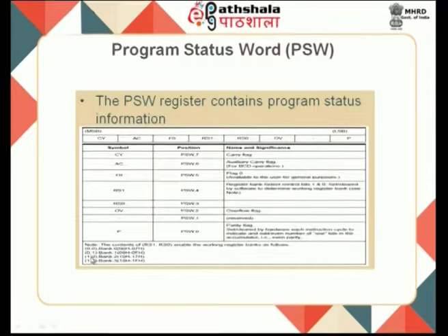What are all the addresses through which we will be using that particular register will be decided by RS0 and RS1. This is a combination, so I can make 2 bits, 00 to 11. Rather, you can look over here: 00 will be bank 0, where the address for your R0 to R7 is 00 to 07, whereas 11 means bank 3, 18H to 1FH. So, this will be the place.